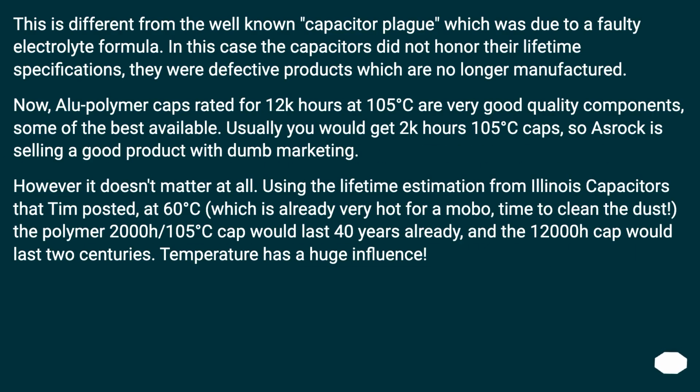This is different from the well-known capacitor plague, which was due to a faulty electrolyte formula. In this case the capacitors did not honor their lifetime specifications, they were defective products which are no longer manufactured. Now, alu polymer caps rated for 12K hours at 105 degrees Celsius are very good quality components, some of the best available. Usually you would get 2K hours 105 degrees Celsius caps, so ASRock is selling a good product with dumb marketing.